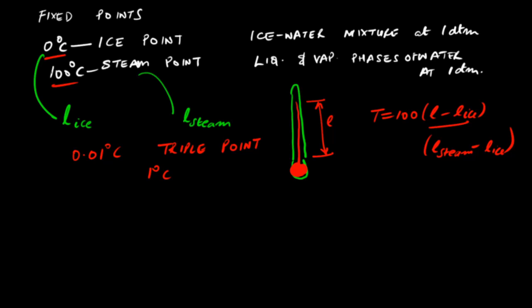So a similar procedure you can do for any different type of thermometer, and you can define different interpolation rules to interpret temperature. Here we've assumed that the volumetric expansion of the mercury behaves linearly with temperature. That's why we can, let's say, divide this scale in equal gradations. But you might have a nonlinear relationship. Typically, for a resistance-based measurement of temperature, you may have a nonlinear relationship between the temperature and the resistance of the thermometer material.